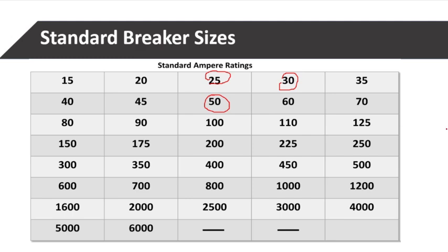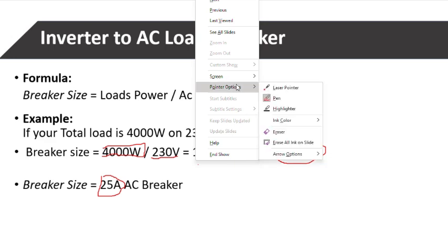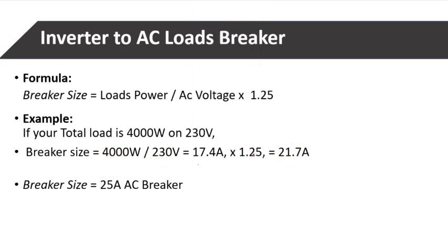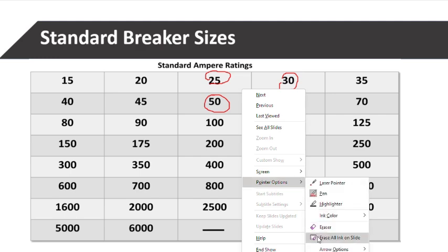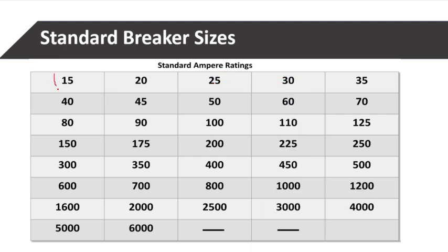That's mistake number one. Then mistake number two is undersizing your breaker. Now for this 4,000 watts of load at 230 volts, they are drawing 25 amps on a go. Now if you come here and install a breaker of 15 amps on a load of 25 amps, and your cable can handle up to 20 amps.